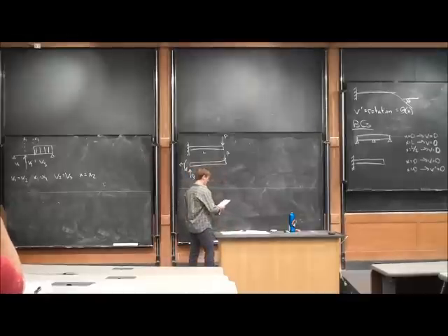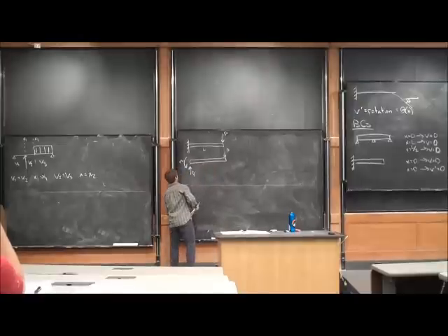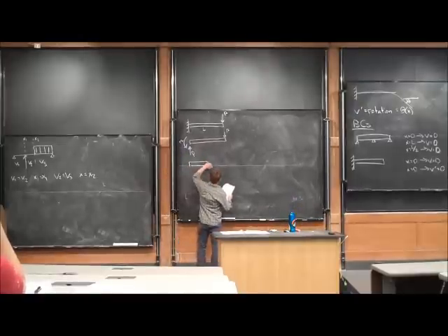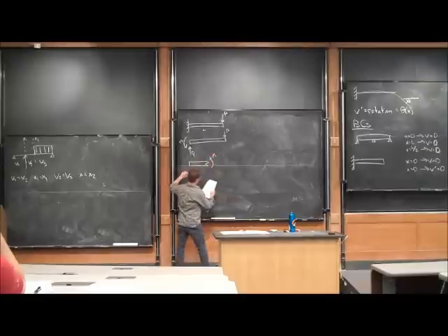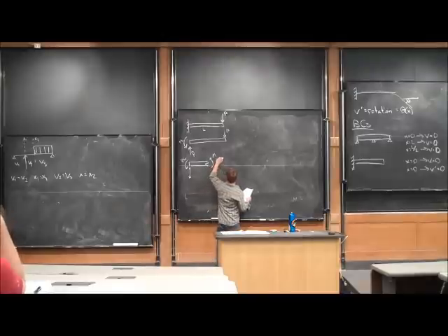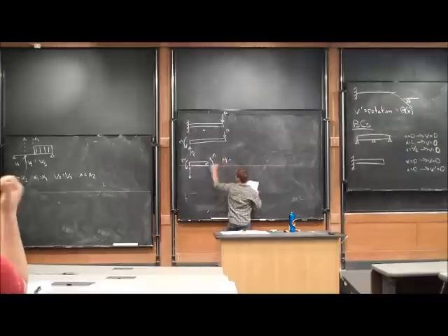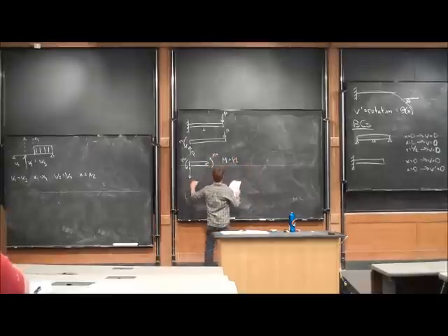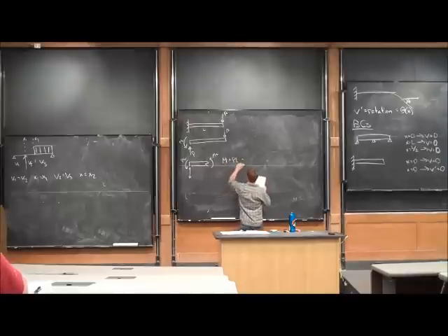When you solve for your moment equation, you have to make a cut. First thing you always do is make a cut. We have some moment, we have P, and we have PL. Based off that, if I sum my moments: moment plus PL, because they're both in the same direction, assuming this is a positive moment, minus P times x is equal to 0.